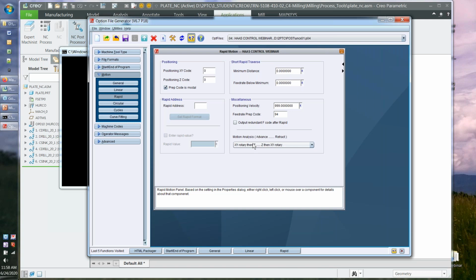Typically, in mill, speaking to 3-axis, if you will, minus certain specific machine conditions that dictate otherwise, most folks do an XY spindle move, and then they follow that with a Z move, turning on the tool length offset and activating the coolant. That sequence of 2 moves is, at least in my experience going back quite a while now, pretty typical in the way people wish to approach the part in a 3-axis mill.